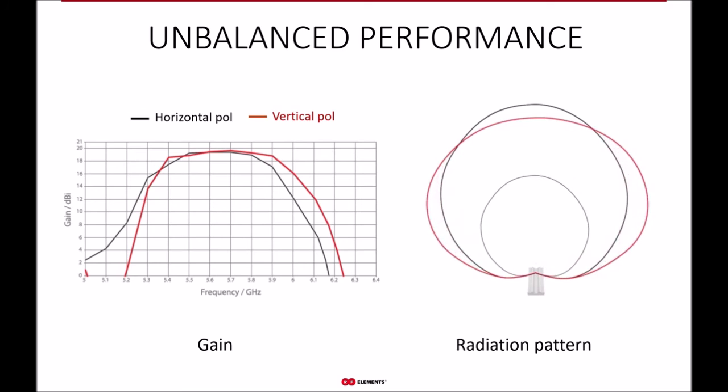The gain of the patch arrays is stable in a very narrow band of frequencies because of the very narrow band nature of the resonances of the patches and the feeding lines, as we explained earlier. So we see that even between 5 and 6 gigahertz, the gain is changing substantially, which eventually reflects into instability of the coverage provided by these antennas.